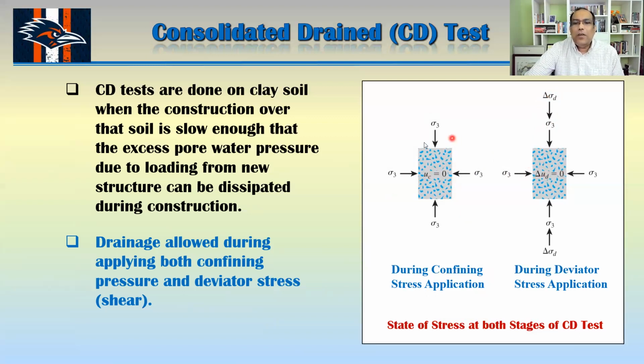One thing I must say here is that even though we are saying this is the force for shearing, we don't actually apply any shear force here. We use the normal force on this particular plane, but that causes stress transformation at different planes of the soil, and the soil will fail at an angle here, which we discussed in our first video, and I'll talk about that again in this video too.